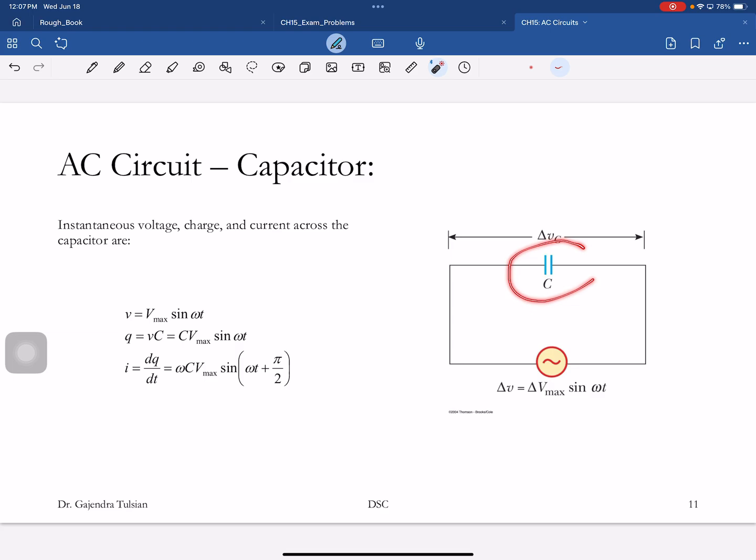All right, so now let's connect the third element that we know. There's the voltage. For a capacitor, capacitance is defined as Q(t) over V(t). So Q(t) is V(t) times C. So V(t) times C, and that's the voltage that the capacitor sees.